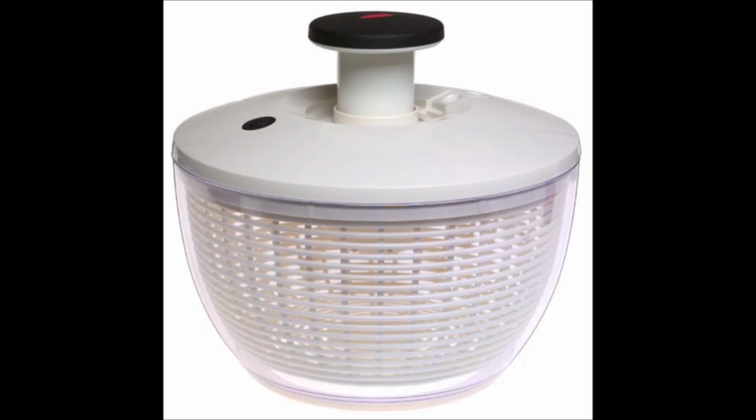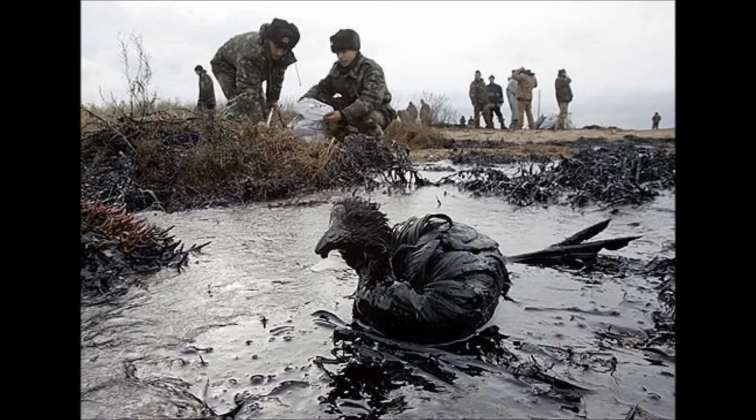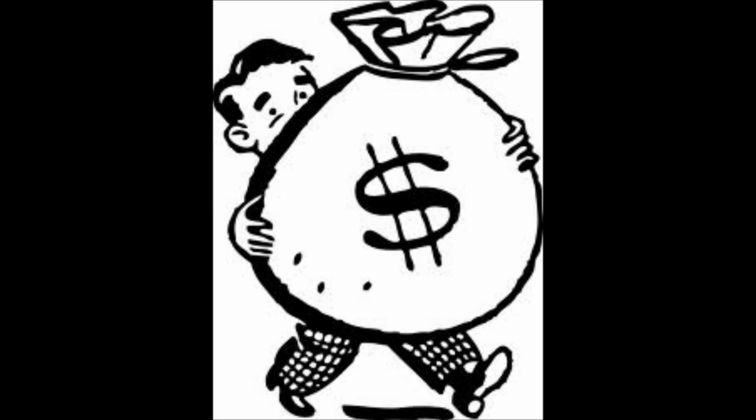This will have to be separated in a centrifuge, and the resulting liquid will have to be purified via distillation to acquire 1,4-butanediol. The unwanted distillate would contain many alcohols and 4-hydroxybutyrate, which, if not handled properly, could be environmentally hazardous. Therefore, this distillate should be distilled again with 4-hydroxybutyrate being put back into the reaction, and the alcohol sold.